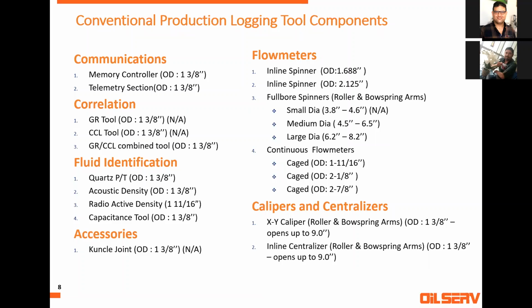So the next group is the flow meter, which will sense the flow rate inside the wellbore, the flow rate that comes to the wellbore, the flow rate that is taken by a thief zone. In case you are injecting, it's called intake. Where does it go to which pay? In case you are producing, it's called inflow. Okay, and the flow meter will give you the unit in RPS, which you need to transform to a velocity value using something called spinner calibration. We'll talk a little bit about that one in the next slides.